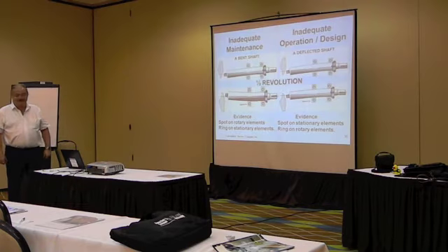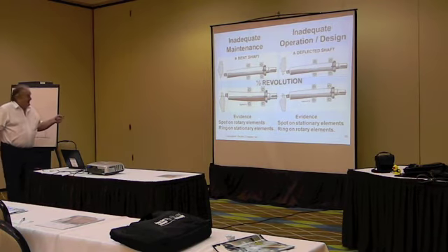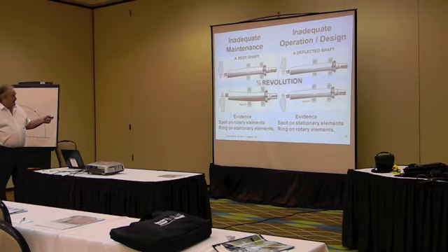Now, this is the difference between a bent shaft and a deflected shaft. This is a bent shaft. It's bent downward like this. 1/2 revolution, it's bent back upwards. This would be a problem with maintenance. We have a physically bent or distorted shaft, and the mechanic is installing it because he doesn't know that it's bent. Now, when I say bent, you can see this, but I'm talking about 3/1000ths of an inch. Okay? So sometimes you can't see it.